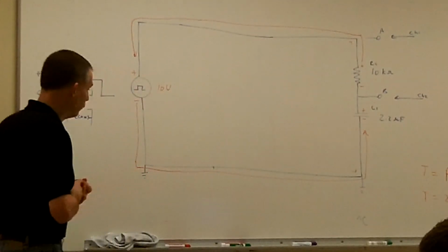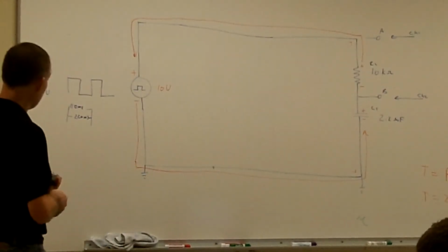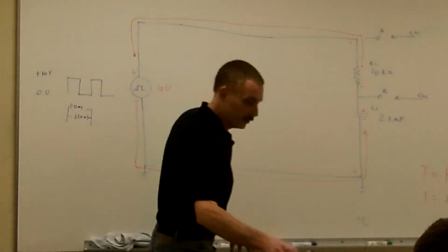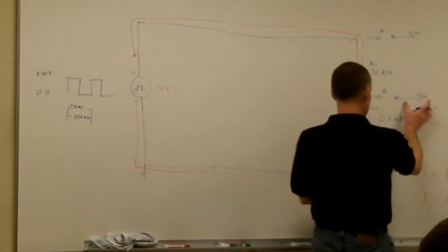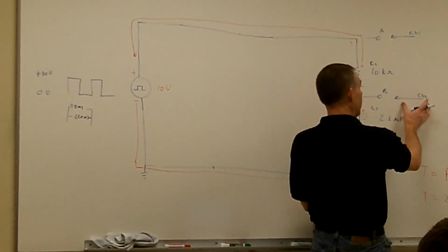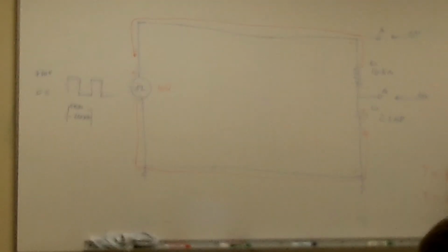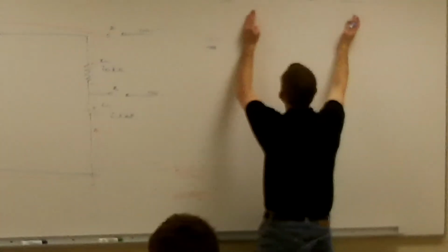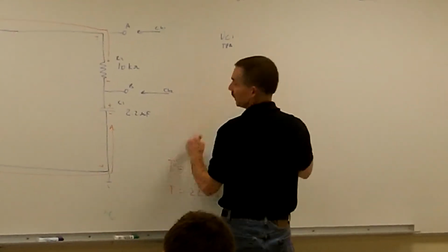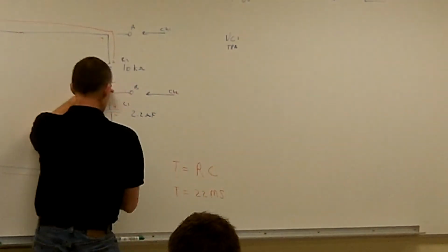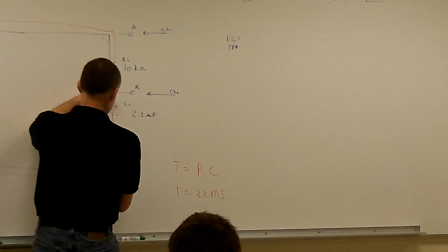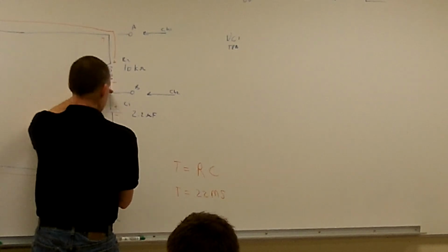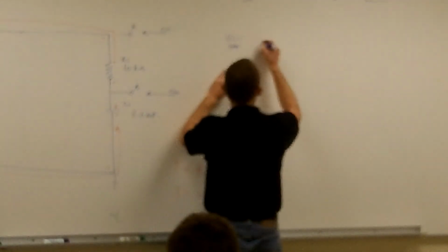So we know that we're going to charge up the capacitor to its full capacity at 5 time constants. So what's going to happen then is that if I'm watching the voltage on channel 2, the voltage across that capacitor, and I'm lining it up with my voltage source, what I'm going to see on my capacitor is that it goes from 0 volts, because when I first applied the power, once that first positive pulse came in, my capacitor acts like a short, so it's going to start out at 0 volts.